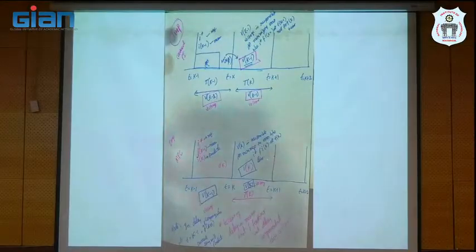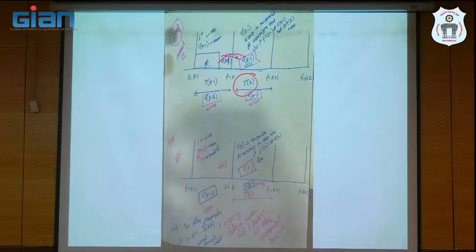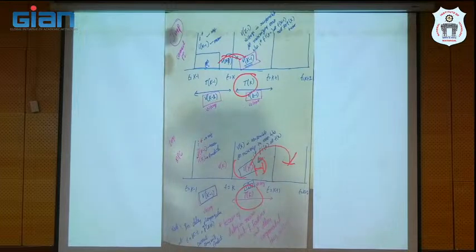This slide gives a comparison between the PI controller and the model predictive controller. In the PI controller, at the kth instant we calculate the error, and for that you need to take information from the previous sample. Everything comes from the previous sample, and that will not give a sufficient response. But here, at the kth instant, we are predicting the voltage vector for the next sample period. If you apply that voltage vector in the next sample, your error will come down.